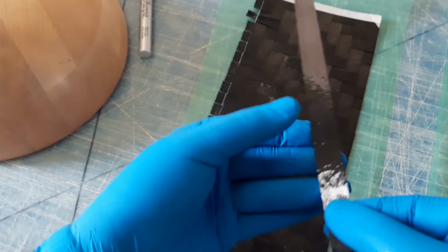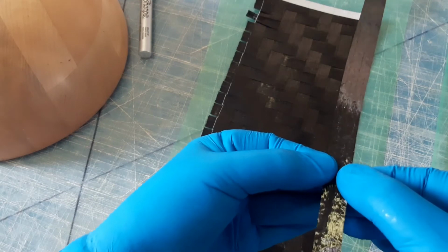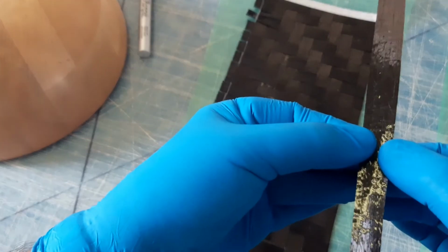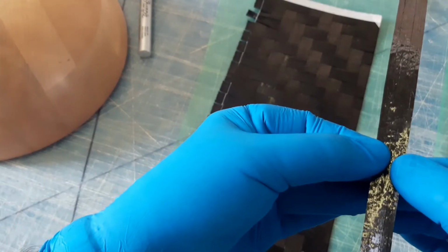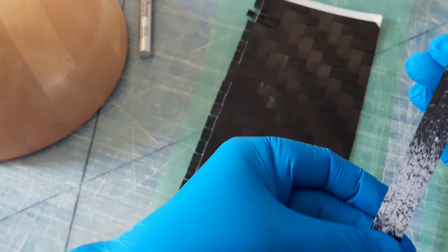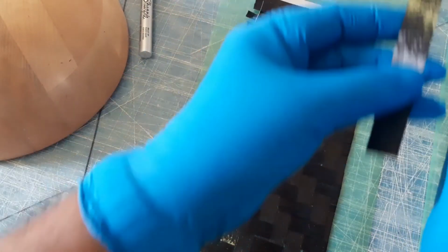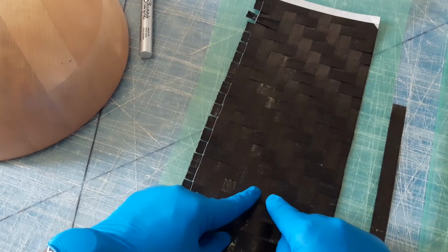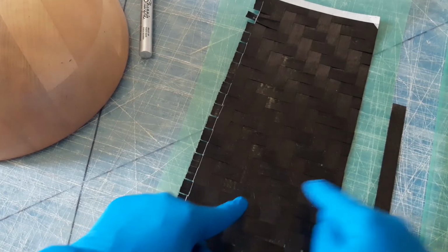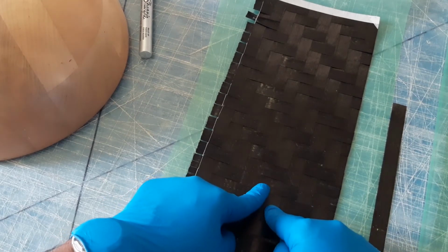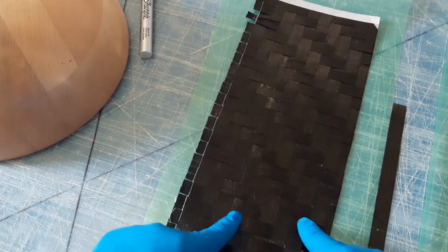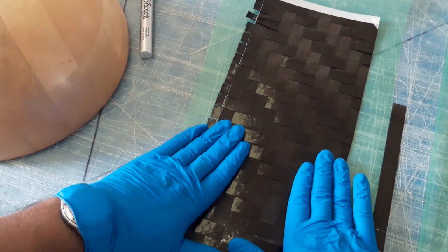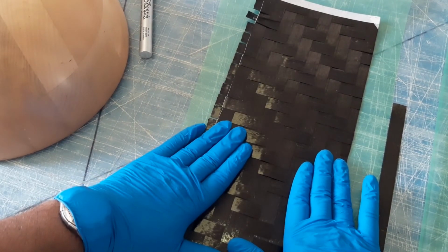The problem with this is that it doesn't have any shear between the bundles. The bundles will break apart, although the fibers will not break, but the bundles themselves do not allow any shearing in the layers over here. The shearing can only happen between one fiber tape and the other fiber tape. So if you try to shift it, you see that it doesn't shift at all.